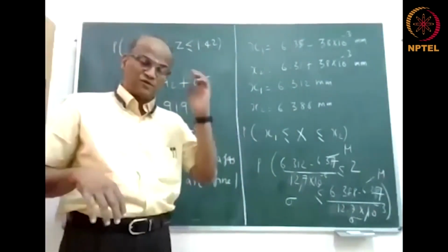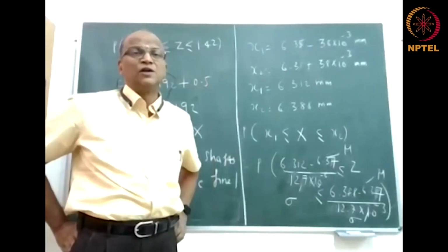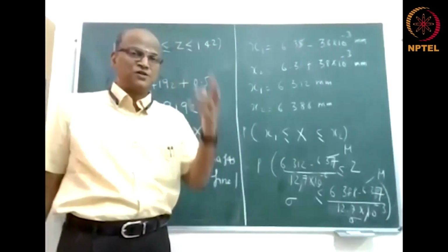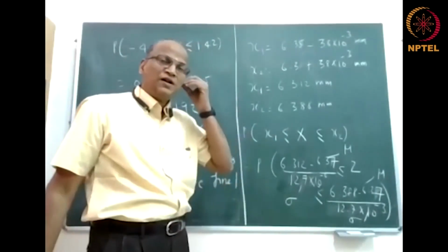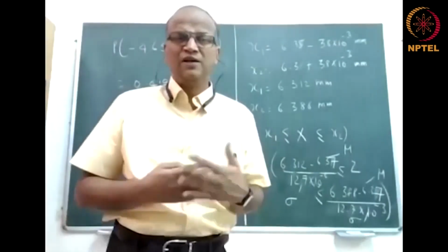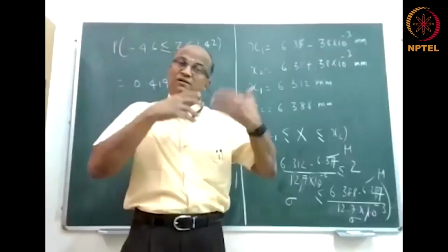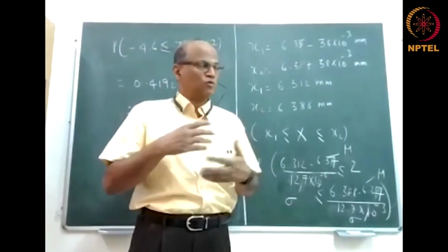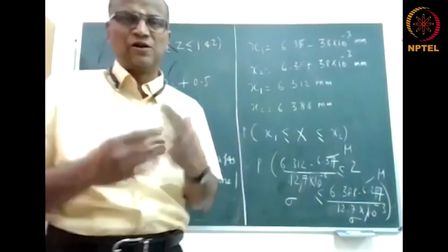Okay, so that 8% also you want to reduce further, then what you have to do is the dimension tolerance has to be reduced. That means you should have a much better machine, and then you should have much better measuring accuracy. Increasingly that is a challenge, as everything has to be made more and more accurate. The tools and the machines required for making these things also have to be more and more modern. Okay, so more expensive and tighter tolerances and so on.